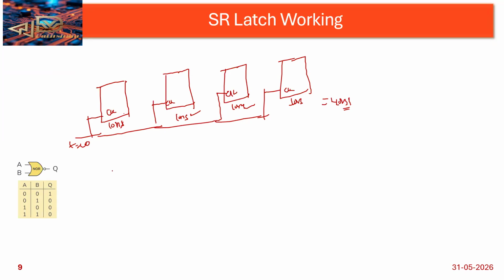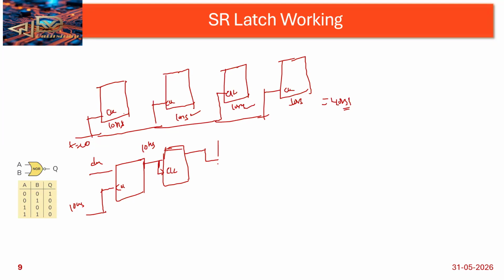Yes, sir. Why? Because the output will be generated like a ripple, ripple type. So here only I'm giving the clock, that is 10 seconds delay, and giving the input, then this output I'm getting, then this output will be given as a clock to the next circuit. First circuit only, 10 seconds delay will be there, and for the next one there is no delay. Again I'm getting the output, and again here. So total delay is 10 seconds only.